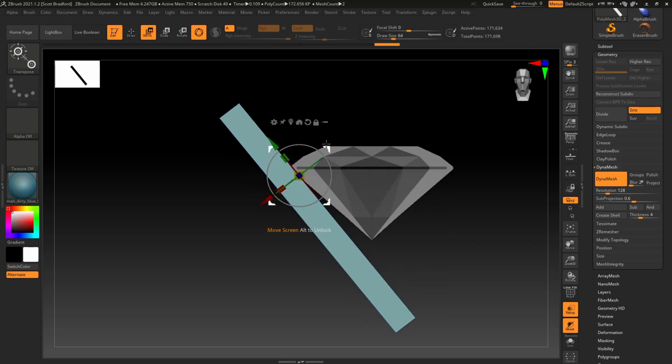Next thing we need to do is reorient our Gizmo, because we're going to be chopping off this extra bit up here and this little corner down here. At the top of my Gizmo, I'm going to hold Alt to unlock the Gizmo and click Reset Orientation. There we go. Now our Gizmo is reoriented to the axes, and we can cut these off a little easier.